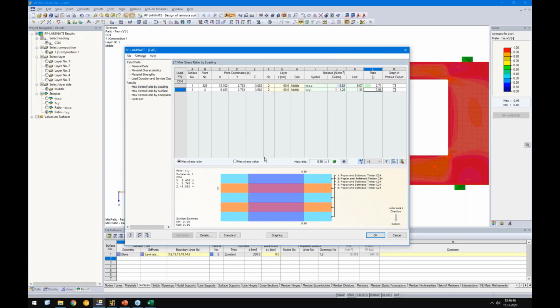So now we need to evaluate the results. And for the surface design, we need to go away from thinking about member design where we have a clear ratio. Because of the singularity, I recommend you follow this procedure. It makes no sense to check here the smiley if it's red or green. You need to evaluate it at once.